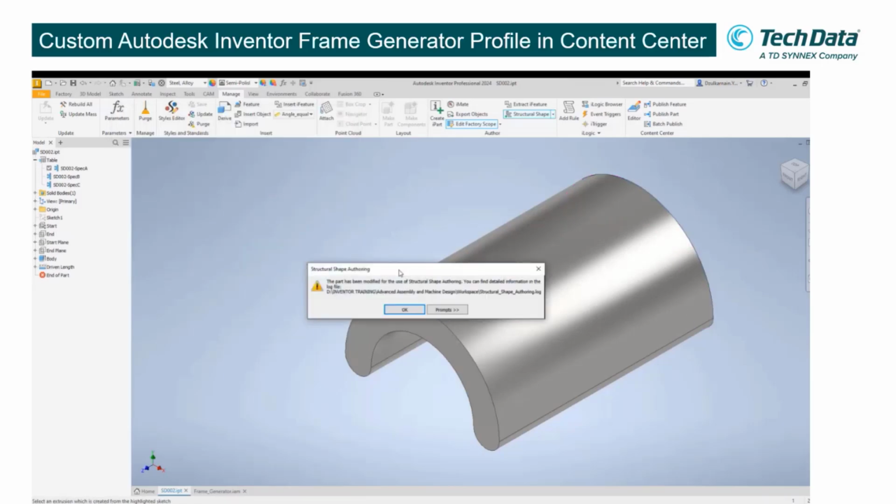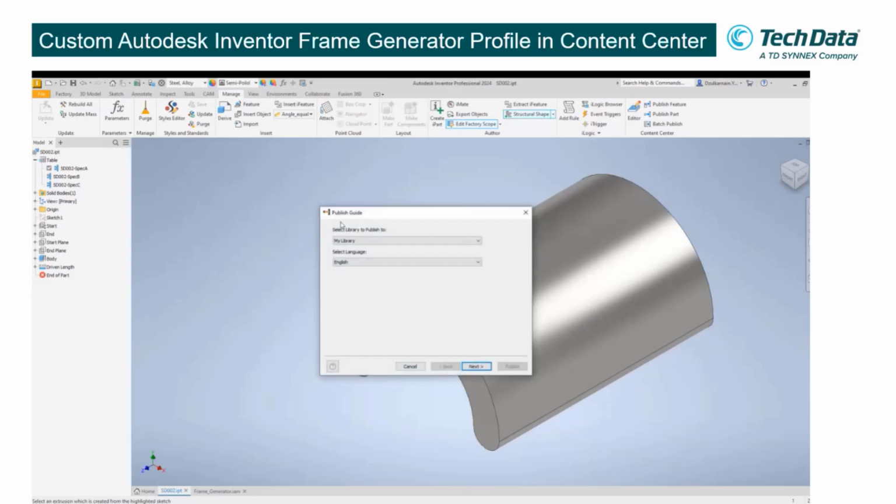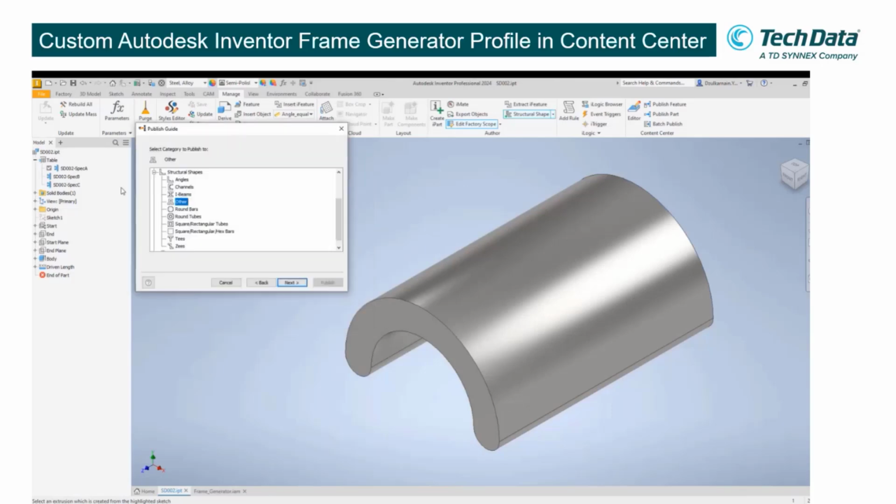Okay, it's telling you the part has been modified and has been added into the library. So, publish guide: select the library to publish to. It needs a read-write library. If you don't have a read-write library, it will not show here. Like just now I created a custom content library, but it's not showing, because probably I did not enable it. So let's just save it into my library, same category, other.